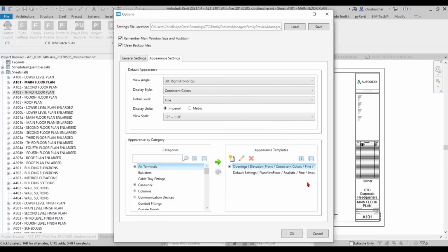All right, so now anything that's an opening, a door, a window, I would want to put on this. So a wall hosted item potentially. But if there's anything else in here that you want to include, go find it, right? So in this case, I have other possibilities here for doors. I can have roof hatches. I could have ceiling-based ones, but those aren't going to look very good in an elevation, so that's why they're not included, right?